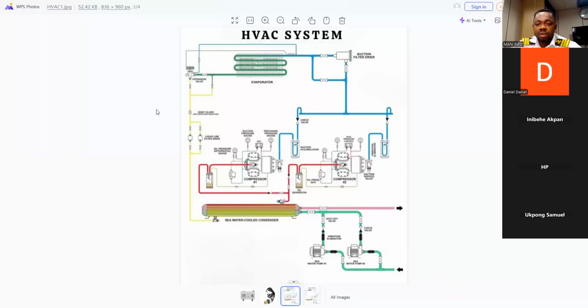Okay, Chief. My question is, do all compressors have this oil separator, or in some of them is it embedded inside? Because on some compressors I will not see any oil separator there. This is mostly in industrial AC, that's where you have an oil separator. For example, in your automobile, the oil moves around with the refrigerant, right?